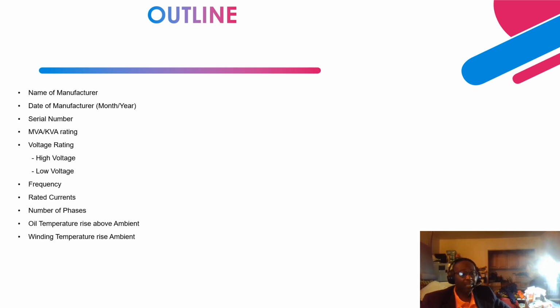Next is MVA or kVA rating. As you know, transformers are output rated. The reason they are rated in MVA is that the connected load power factor varies. So you cannot have a transformer that is rated in megawatts or kilowatts. It has to be rated in MVA.